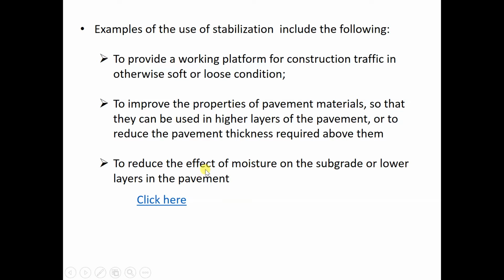If you stabilize with lime, then the lime will provide volumetric stability. So the clay will not swell or shrink when there's a change in the moisture content. Okay, so it can provide that stability.